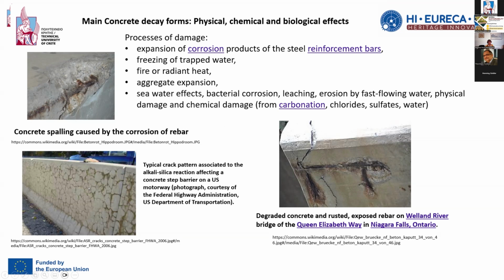Here in this image, you may see a typical crack pattern that is associated with the so-called alkali-silica reaction that takes place between the gel of cement that is in the concrete and some specific aggregates that contain formulas of silica that are reactive with this gel.